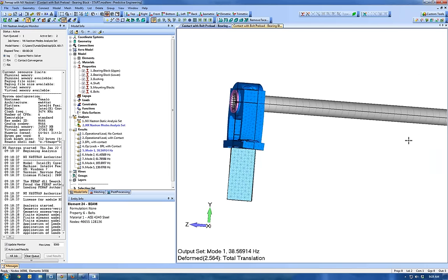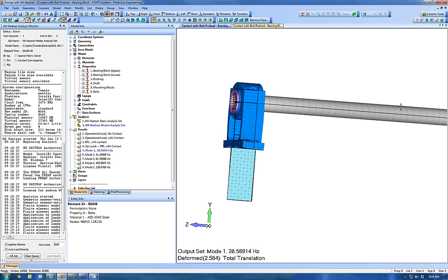So as this shaft moves up and down without any sort of contact or bolt preload, the stiffness in that direction is really highly dependent on the bending stiffness of those 2 bolts. Once we incorporate contact and bolt preload, we're actually getting the interaction between the pillow block and the pedestal and transferring the load a bit further out from that center line of that bolt.